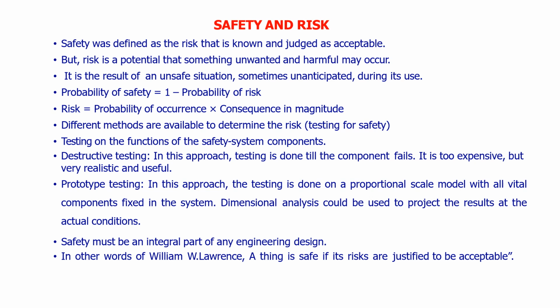Another approach is the prototype approach. The testing is done on a proportional scale model, with all vital components fixed in the system. Dimensional analysis could be used to project the results to the actual conditions. A prototype is a working miniature with all the components. It is very similar in working condition to the new or actual product. We can conduct various tests and project the results to the actual conditions. That is called prototype testing.